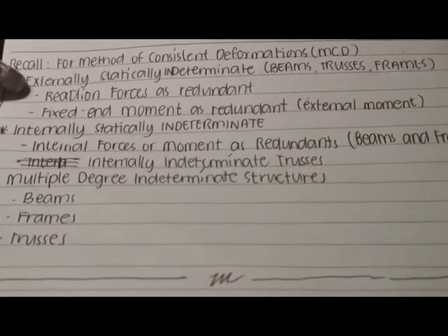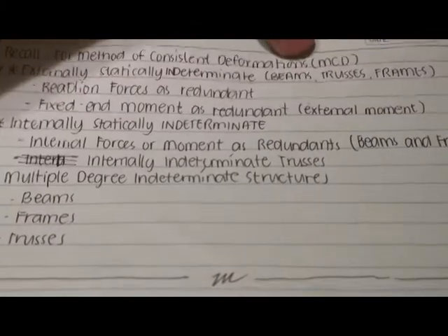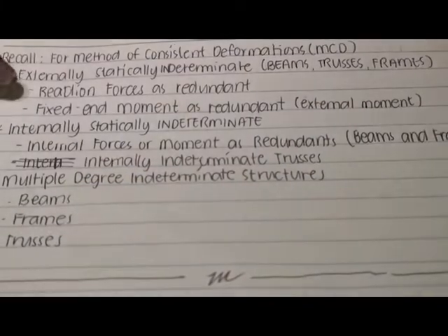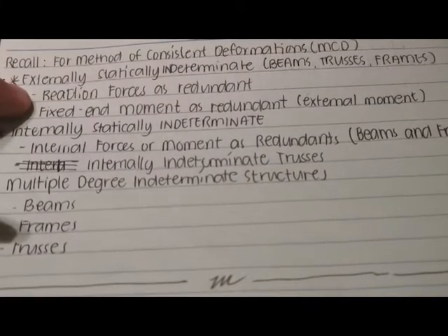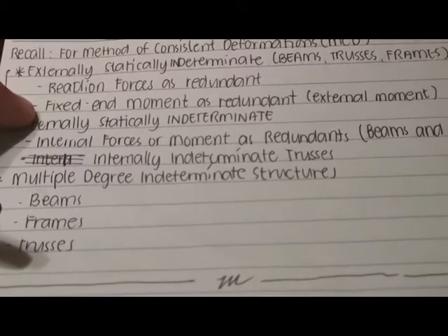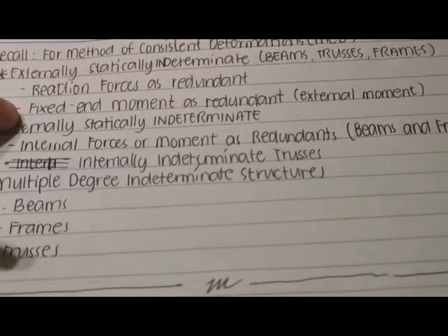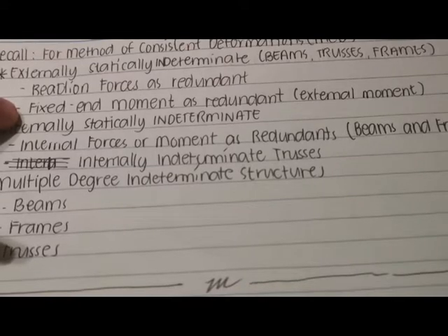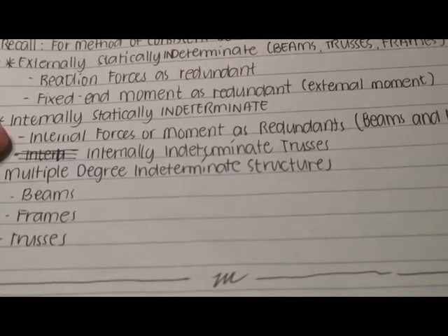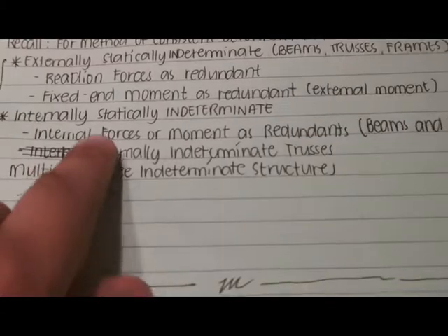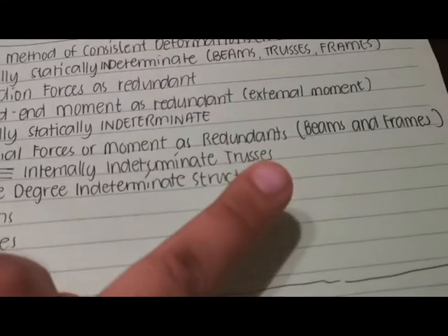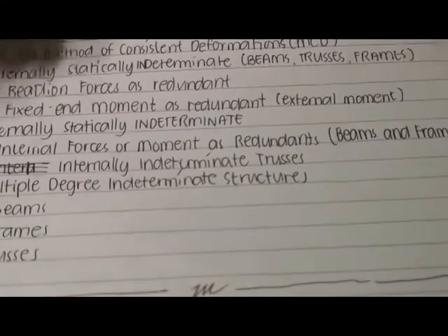For externally statically indeterminate, which is applicable to beams, trusses, and frames, we consider either reaction forces as redundants, or fixed end moments or external moments as redundants. Next, in the case of internally statically indeterminate structures, we either consider internal forces or moments as redundants, for beams and frames, and internally indeterminate trusses.